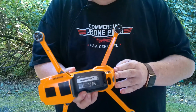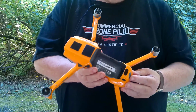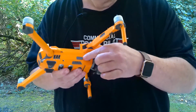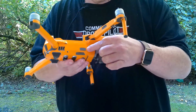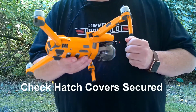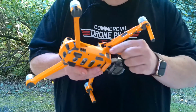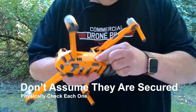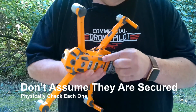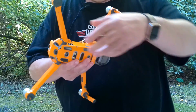So if everything looks intact and you can't see any problems, you need to turn your attention to these hatch covers that you'll find on the outside of your aircraft. Depending on what type of drone you're flying, they may be in a different place. But you need to ensure that these hatch covers are correctly seated and firmly pressed into place, because it doesn't take much to jar them loose.